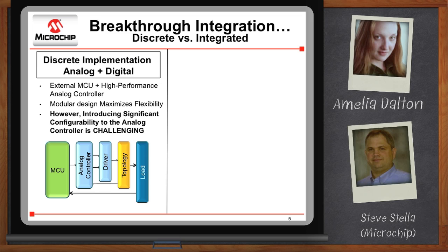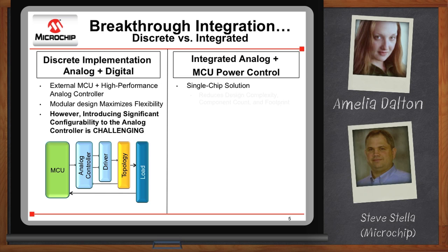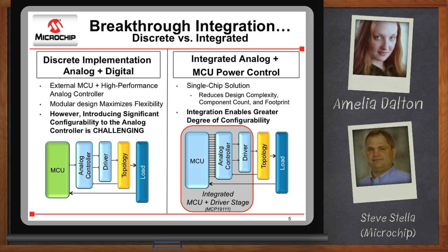Yes. So now we're able to integrate a microcontroller with the analog controller and even some other mid-voltage components, including MOSFET drivers and LDOs, so that we combine a fully functional, very flexible analog-based control solution with that digital interface. Very cool. So I'm definitely in favor of integration as a whole. Less stuff on my board, smaller bill of materials. You're exactly right. And that's what the technology enables.